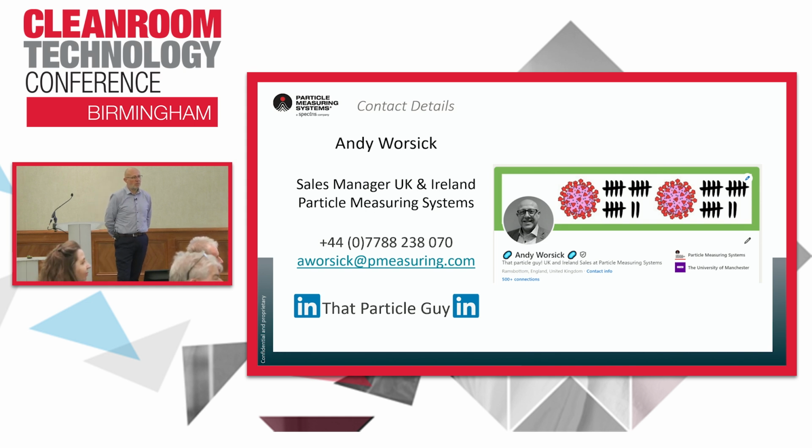Thank you, Steve. Gordon Farkas. Remember that in the GMPs now there's very common talk about first air. The assumption is that we're interested in that air derived from the HEPA filter at a critical control point, and that we're demonstrating there's nothing interspersed between that air source and the sensitive critical task.